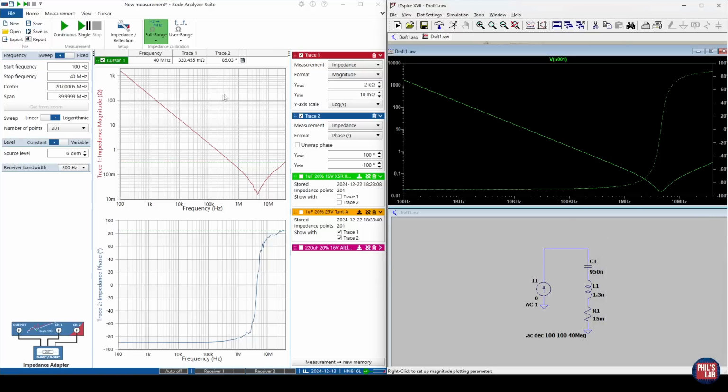model parameters, and we can see both the magnitude and the phase seem to align quite well for this specific operating condition. So with this very, very simple model, not even including the leakage resistance, we get quite a good fit between measurement and simulation.